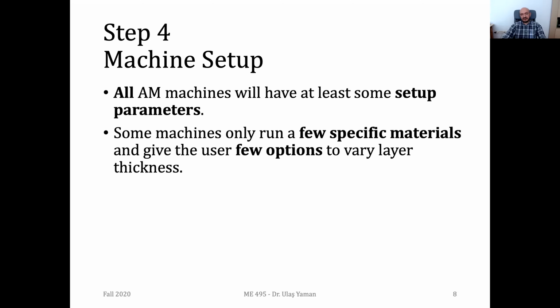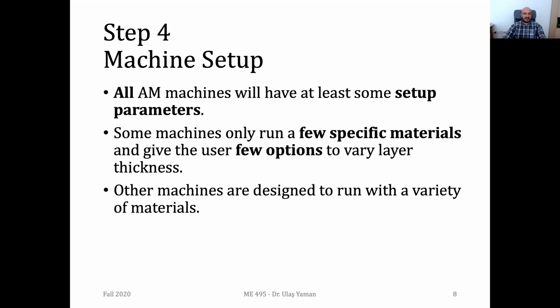So you should first check the material and then adjust other parameters. And you may also have some default parameters for specific ones, so you don't need to spend much time on it. By simply selecting the appropriate material, your CAM software will arrange the other parameters.